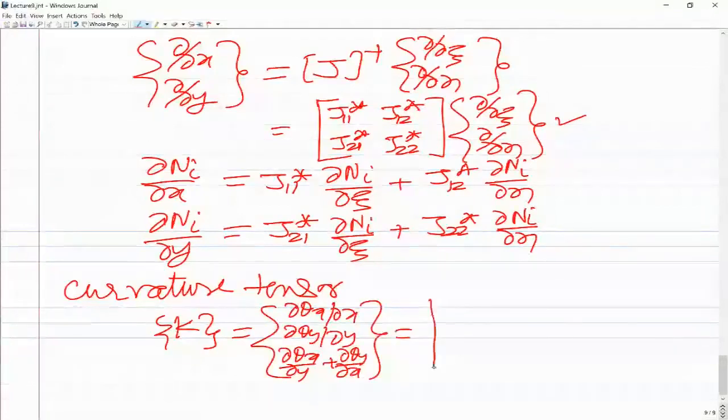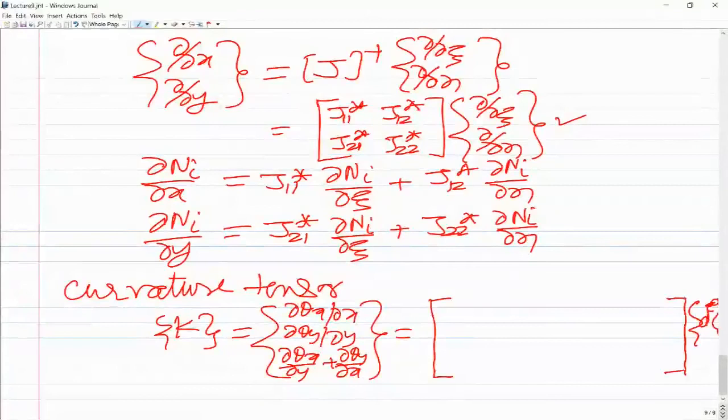I will write only a few elements, and you can do the rest yourself. And into the D, the vector of elemental degrees of freedom, DE, at each node we have 3 degrees of freedom. So D would be a vector of 3 into 4, 12. So D is going to be a 12 by 1 vector, and this would be 3 by 12.